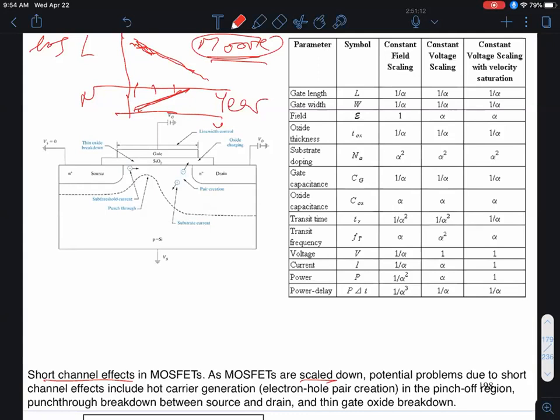The question, of course, is why do people want to reduce the channel length of a MOSFET? So that's this dimension. But clearly, one advantage is if you make the transistors smaller in size, you can cram more of them on a certain piece of silicon, and you can have a larger number of transistors on your IC, right? In a modern IC chip today, you'll have, like I said, billions of transistors in a piece of silicon, maybe 1 inch by 1 inch. And that's what you have in your Pentium microprocessor chips in your laptop, for instance.